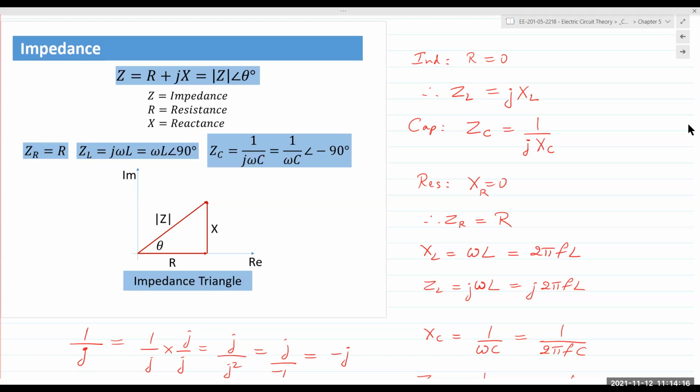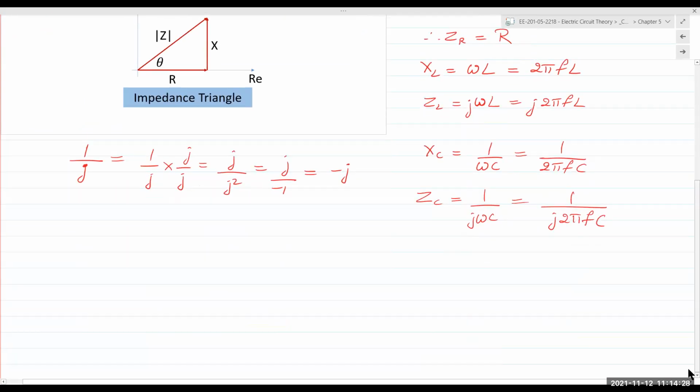Okay, so whenever you read the words imaginary reactance, it is not something that's just coming out of thin air. It's a mathematical representation that is imaginary. So for a resistance which does not have any energy storage, reactance is equal to 0. Okay, for a resistance, reactance is equal to 0. So if we write ZR would be R plus JXR, sorry, XR, and there is no such thing as XR, and so ZR is therefore equal to R.